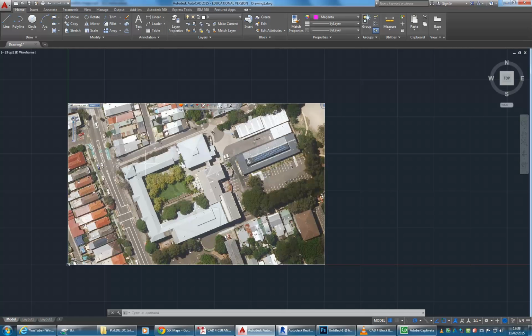And so if you're wondering where true north is, because this is a satellite image, north is straight up. And you can be pretty sure of that with any satellite photo or image that you have. And so the side of the image is going to remember true north. If we rotate this photo, we've still got the sides there to use if we need to find true north again. So we can rotate this pretty freely, as long as you remember that when you take it into Revit, the side is always pointing to true north.